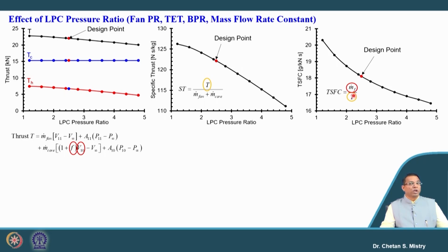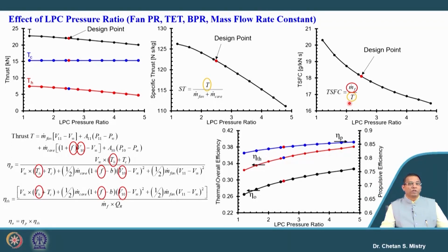Now, let us look at what will be the impact on the efficiency term. Here we can clearly see that with the increase of LPC pressure ratio, our thermal efficiency will be increasing. We will have a rise of propulsive efficiency, and in the overall sense we will have a rise of overall efficiency with increase of LPC pressure ratio.